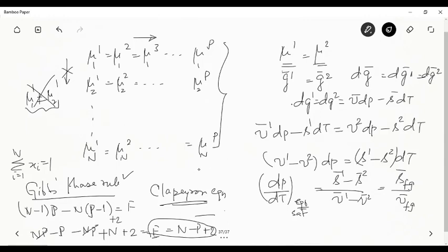So right now we have derived the condition for equilibrium from the basic premise that an isolated system left to itself should go to a state of minimum internal energy when S and V are kept constant, or maximum entropy when U and V are kept constant. And we wanted the condition when T and P are kept constant, so we got that it should go to a condition of minimum Gibbs function when temperature and pressure are kept constant. So phase equilibrium is when multiple phases of the same substance are present in equilibrium when no chemical reaction is happening.